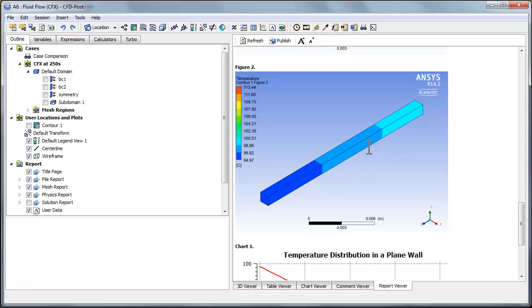I can see a contour plot of the temperature profile through the wall. It doesn't really show me much. Note that I only see the lower temperature scale because this is scaling according to the temperatures over the entire time solution. We started out at much higher temperatures.